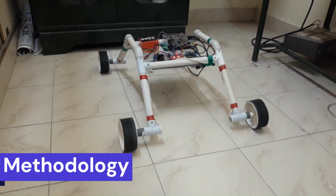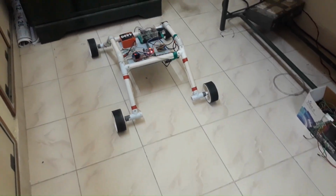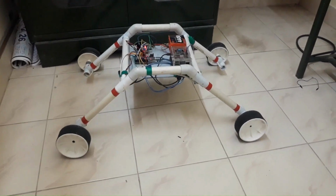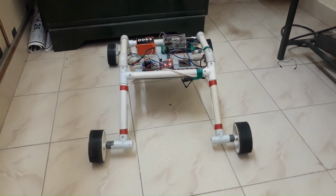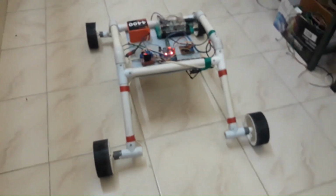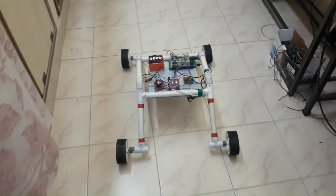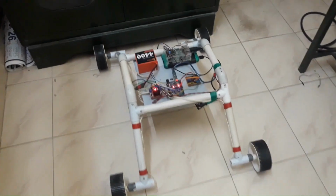Methodology. A robot made for precision agriculture uses a camera which takes pictures of the plant, and the image is processed through an image processing algorithm using Raspberry Pi and OpenCV. The robot also collects individual plant data such as the soil moisture near the plant, humidity, etc. The measured data is sent to a dedicated IoT webpage which shows the plant health in a precise manner, and the data is stored in a database for future analysis. The webpage also gives some remedies for rectifying the plant disease.